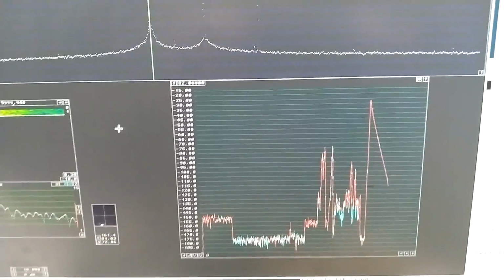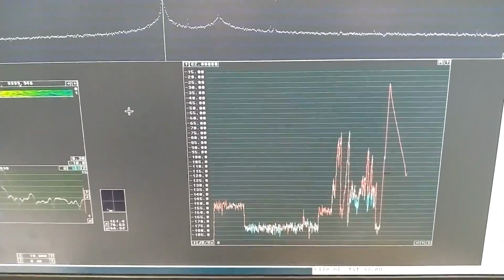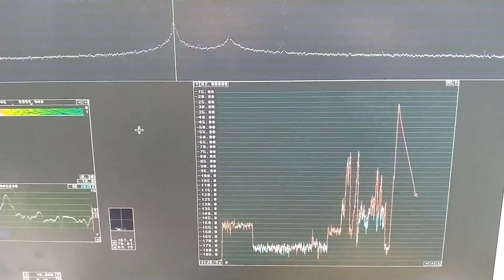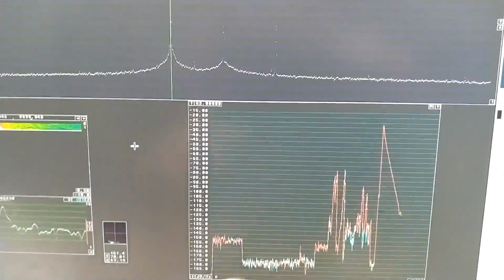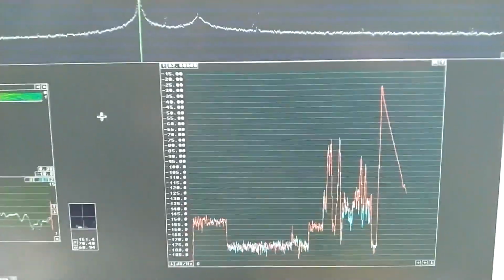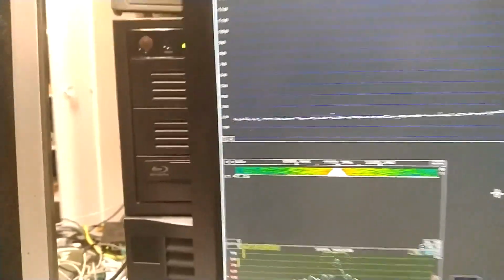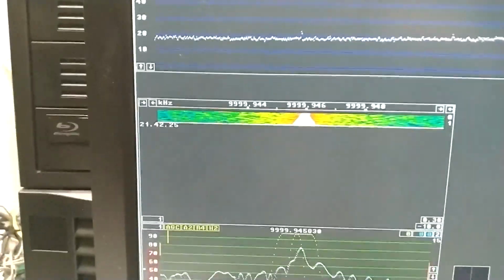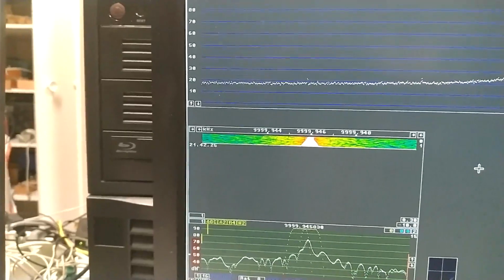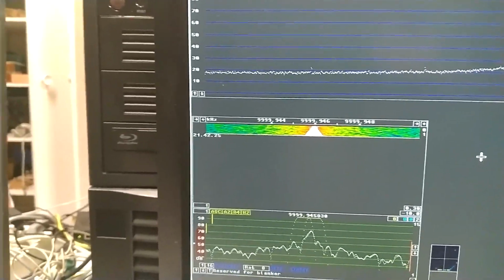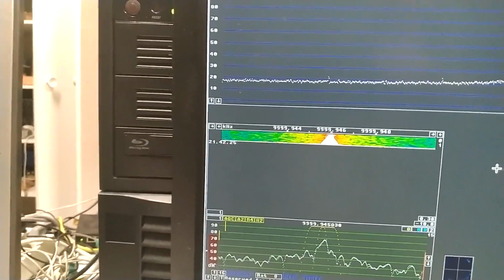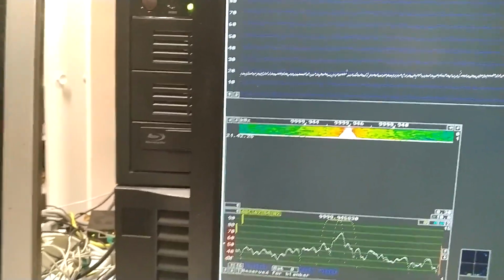I have reinstalled feedback and I have turned down the gain just below the point where oscillations start. And you can see how oscillations are decreasing, and soon there will only be noise. And it is maybe easier to see here. So what I see now is the result from a selective amplifier with a Q multiplier that provides a very narrow bandwidth in which there is noise.